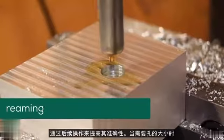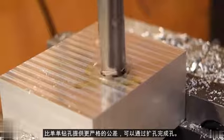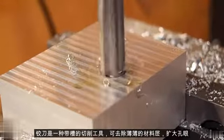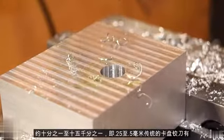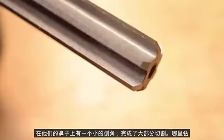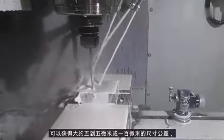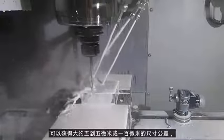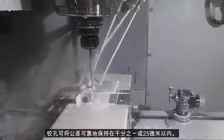When the size of a hole requires a tighter tolerance than drilling alone affords, the hole can be finished by reaming. A reamer is a fluted cutting tool that removes a thin layer of material, enlarging the hole by about 10 to 15 thousandths, or 0.25 to 0.5 millimeters. Traditional chucking reamers have a small chamfer on their nose, which does the majority of the cutting. Where drilling can obtain size tolerances on the order of plus or minus 5 thou, or 100 microns, reaming can reliably hold tolerances inside of a thousandth, or 25 microns.